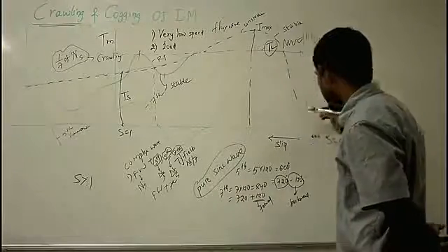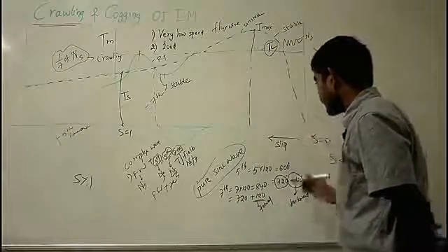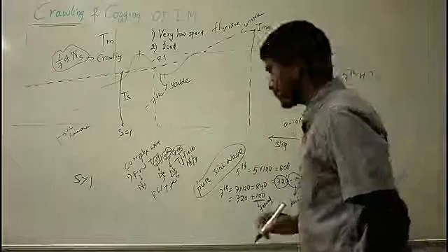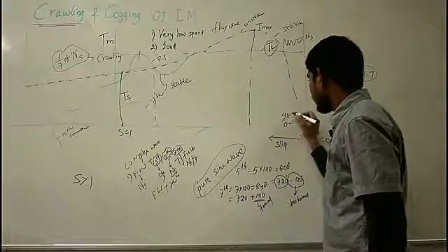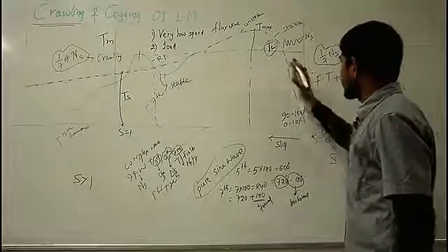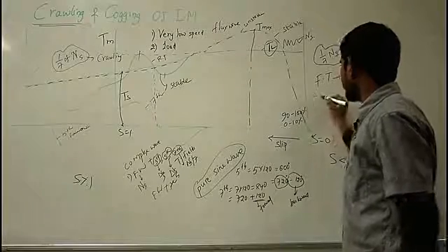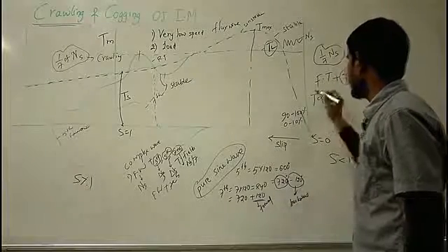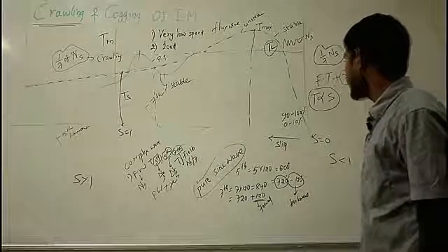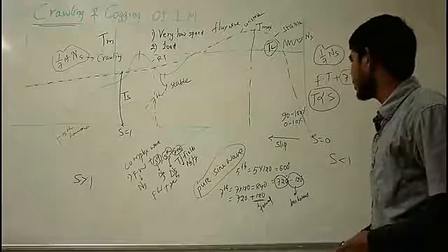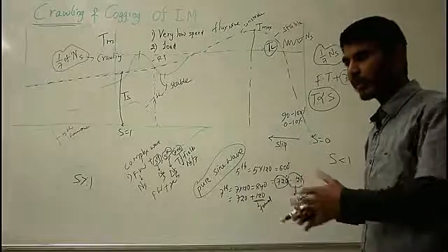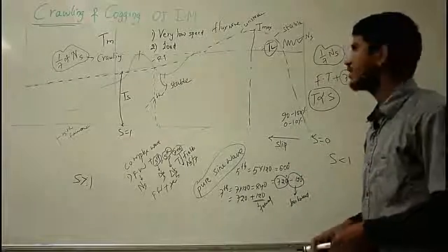Because if you see here, we are having a very low slip, that is, let us say 0 to 10% of slip with a high speed, that is around 90 to 100% of speed. Now, in this region, your torque is proportional to slip, that is, the torque and the slip have a linear relationship with each other, and this linear relationship helps to calculate the motor parameters and simplifies the calculations to a greater extent.